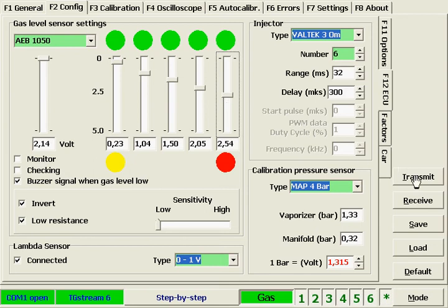Then make a transmission. In order to have this data saved in the memory of the controller, it is necessary to reduce the engine revolutions or switch back to petrol. Let's switch back to gas and watch the indication. We have reached the lowest level and the red indicator is now on. The red indicator corresponds to the empty tank, while all the green lights indicate a full tank.